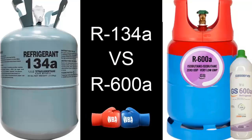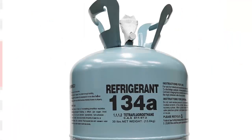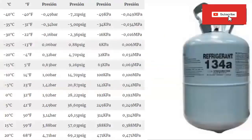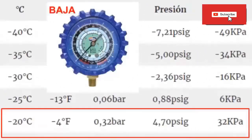Now, let's study in detail the specific pressures of each of these refrigerant gases, where we will observe that the pressures of R600a are very low, even reaching vacuum pressures in low temperature applications. The most used R134a refrigerant gas pressures are as follows. To reach a temperature of -20 degrees Celsius in the evaporator, equivalent to -4 degrees Fahrenheit, a low gauge pressure of 0.32 bars is required, equivalent to 4.70 psig or 32 kilopascals.